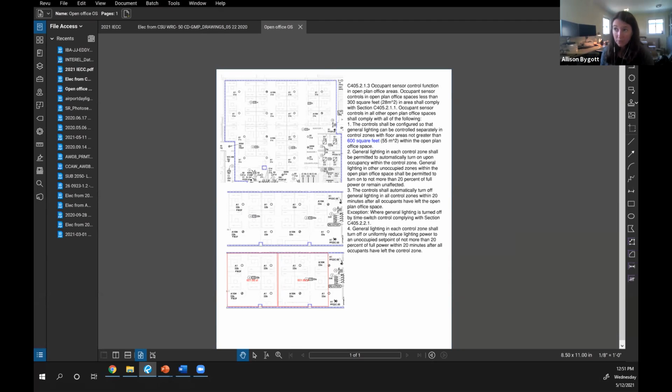I have seen a few vendors in town say, okay, let's compromise. We'll wire the occupancy sensors in the room. That way we get better coverage, we don't have batteries, and we'll do wireless daylight sensors and wireless wall switches. That is an okay compromise, but most of those systems don't show a lot of information in the software, and so I'm struggling to test them.